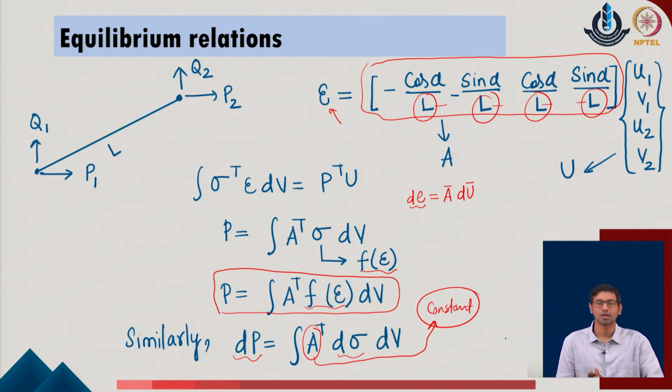So, one should not exactly copy it with respect to the same geometrical stiffness expression, but see that the utility there was defining the change in the length, and corresponding to that we express the term A of the given system, whereas here we are specifically interested to define the strain, which is the change in length per unit length of the given system, and that is why the denominator of L is also appearing in the given system. Okay. So, with this point, now we define that the general relationship between the force increment